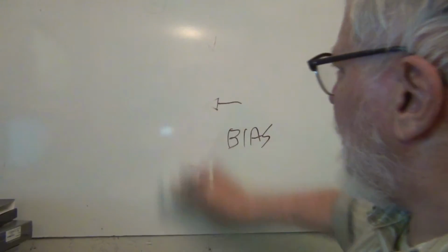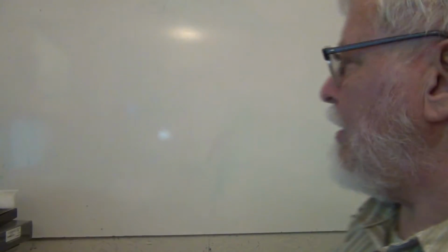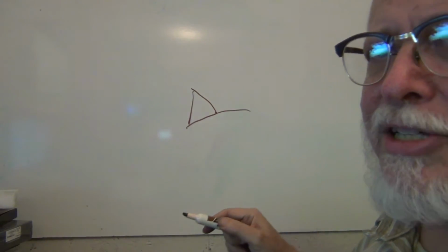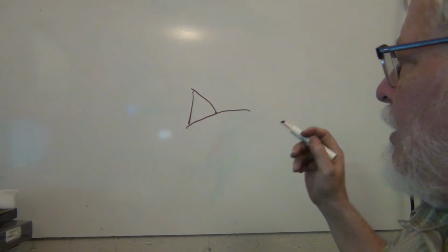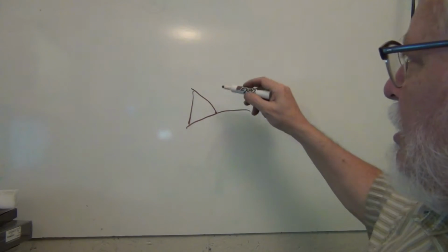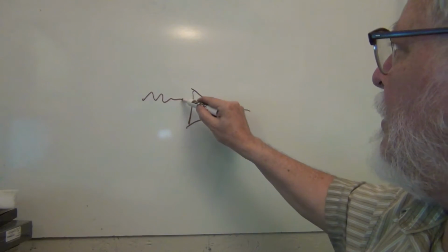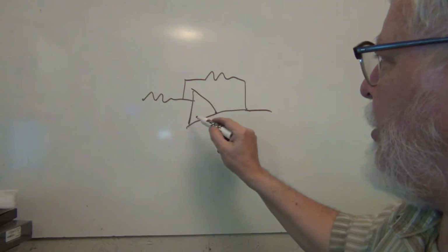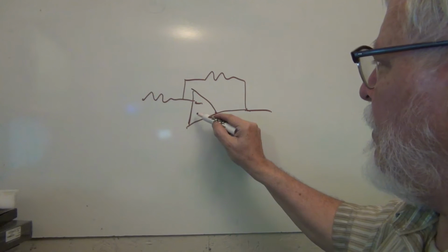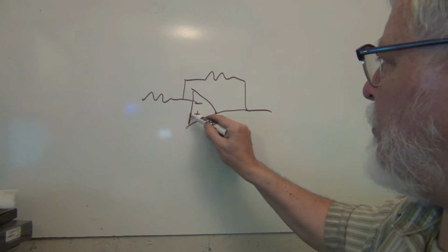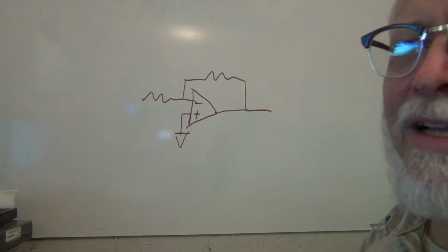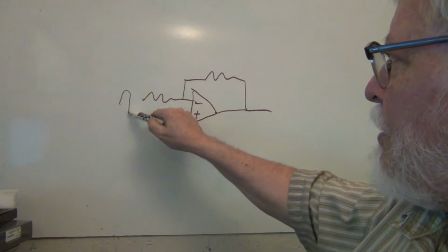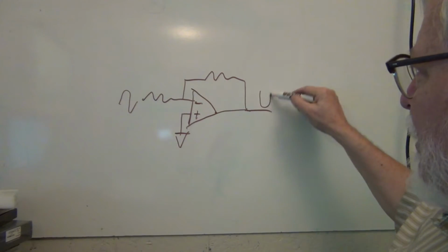All right. The third element that we need to talk about is, in the Scanimate terminology, just a simple summing amplifier. Now, in actual electronics, that's called an op amp, and there's a resistor here and a resistor here. This is called the inverting input and the non-inverting input. So in a regular electronics world, that's an amplifier. If these are the same value, if you put a sine wave in here, you'll get the same thing out here, but it'll be inverted.